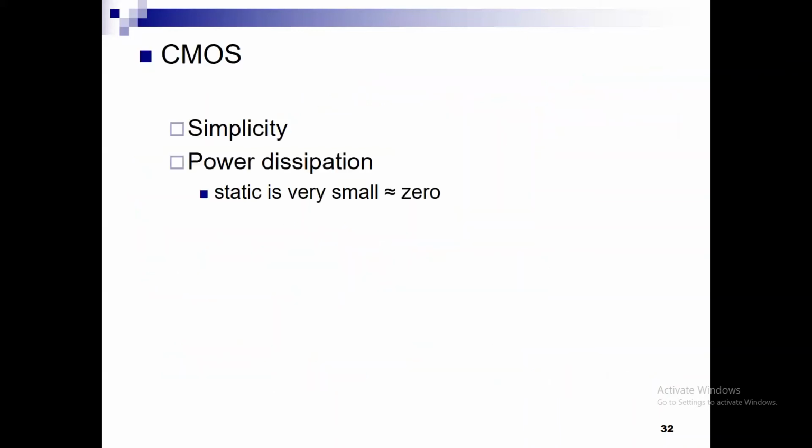Okay, so let us now move forward. First, we're going to talk about the CMOS inverter. And then, in the context of the CMOS inverter, we will use the average current method to solve for the Tp low to high and Tp high to low. We avoided using it for the resistor-based inverter for the pull down because we assume that we have to neglect the presence of the pull-up resistor, and we have 2 devices to reach VOL.